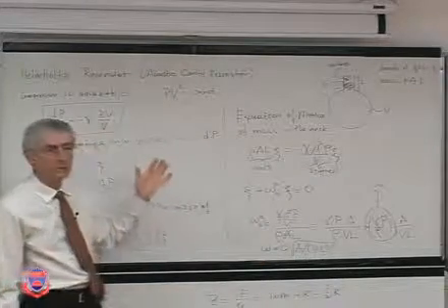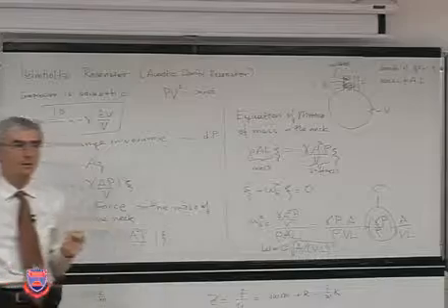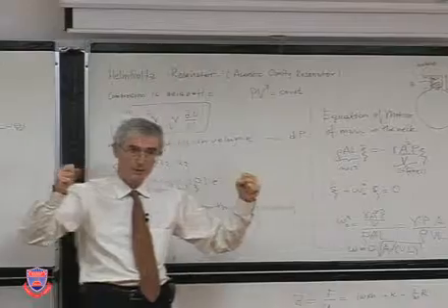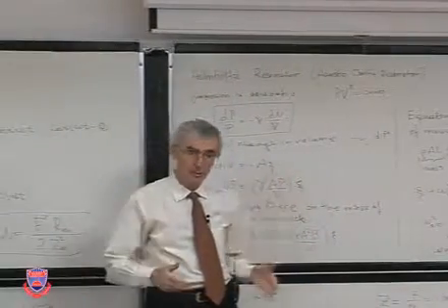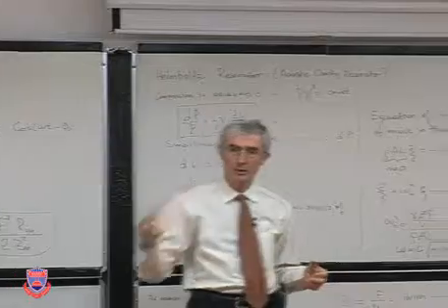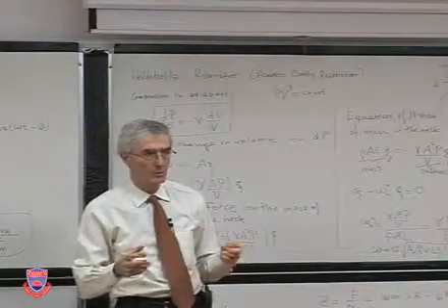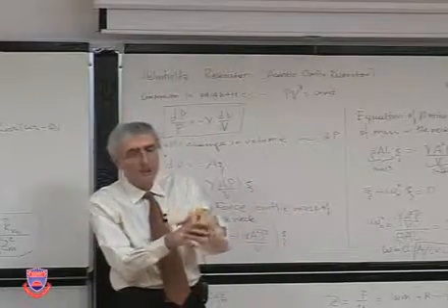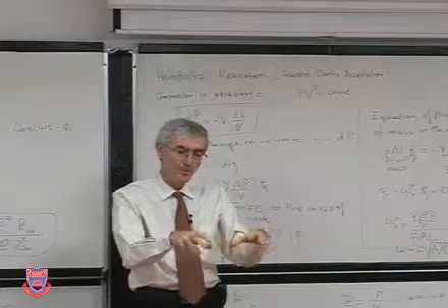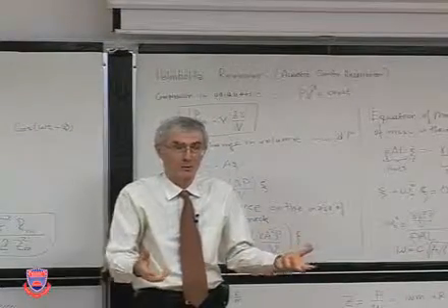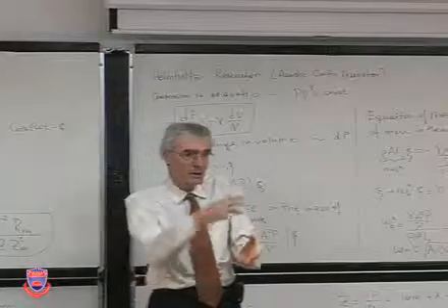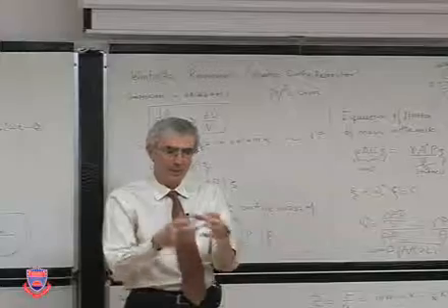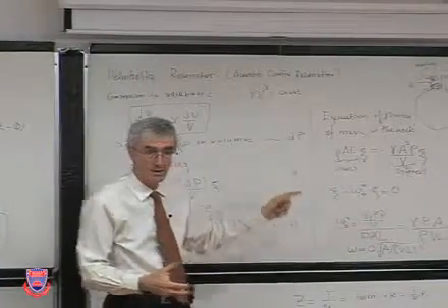Now, what do you use these for? Helmholtz resonators are used in a number of different applications. They could be used as sound absorbers in theaters, in automobiles. What's called an induction noise in an automobile. They actually put a long volume. The shape is determined by how much space is available in the engine, because you don't have much space in the engine. So it can just actually be a very funny shape. It doesn't matter as much, okay? And it acts like a Helmholtz resonator.